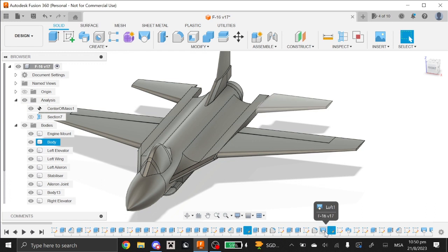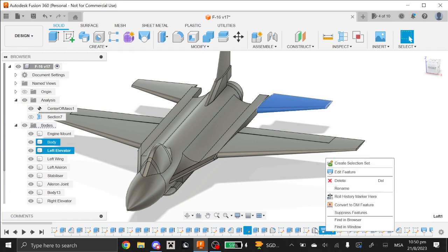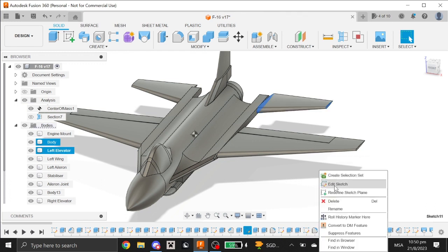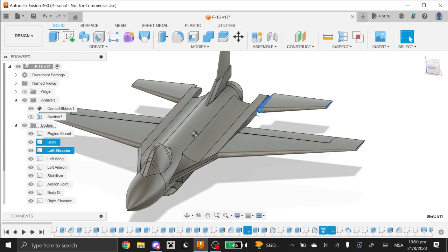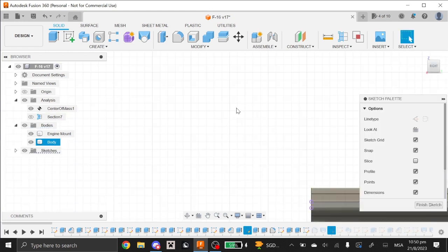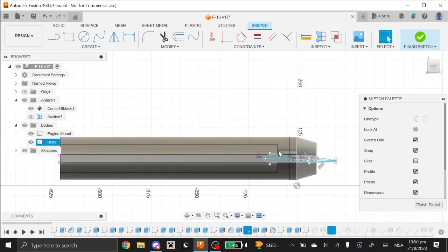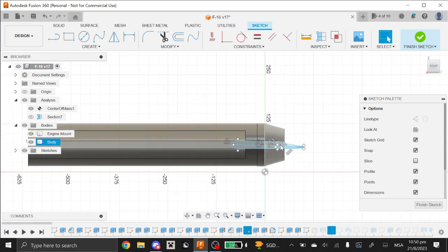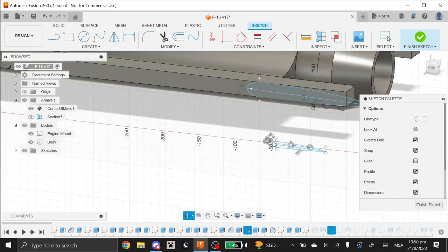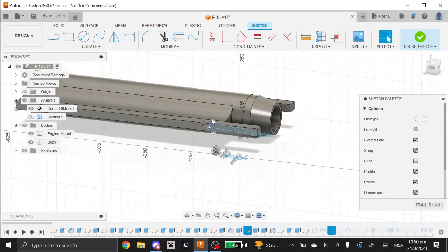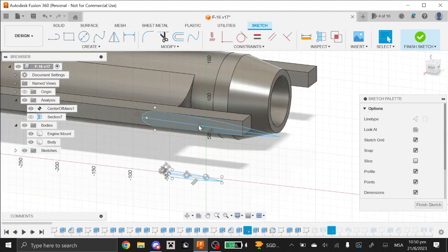You may be wondering how I made the wing. The wing is very simple, so I shall show you. First thing you do is create a sketch, a sketch being on the 2D plane once again. So I make an aerofoil shape on the plane, whichever kind of plane you want. Anyways, you can ignore the straight line through the middle. That's just what I used to calculate wing area.